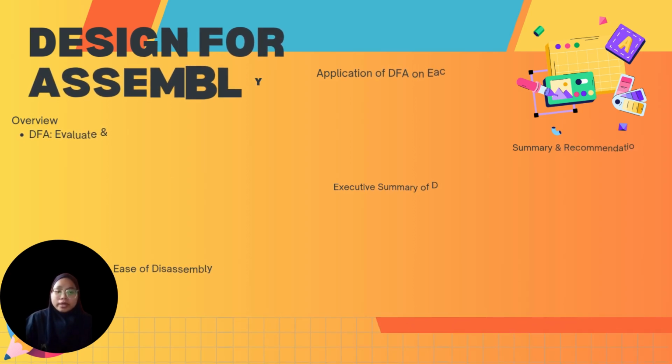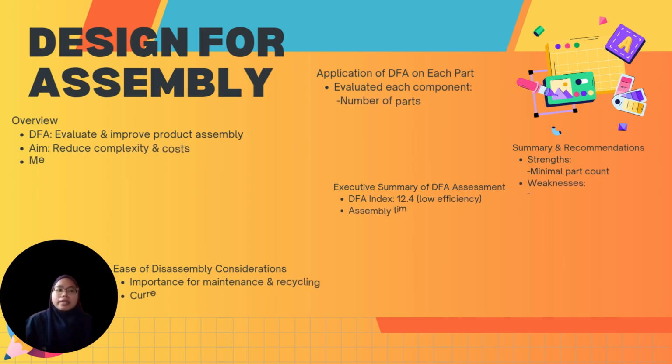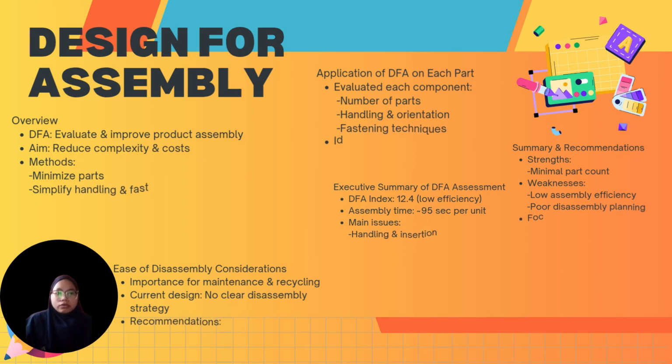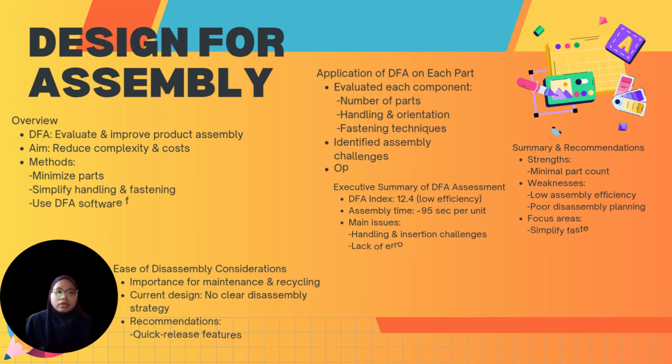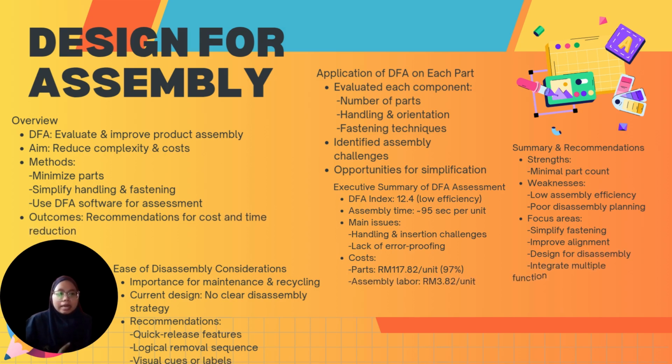Hello everyone. Now I will present our design for assembly, or DFA. DFA is a structure used to improve how easily and cost effectively a product can be assembled. The main goals are to reduce part count, simplify handling and orientation, and improve fastening methods.